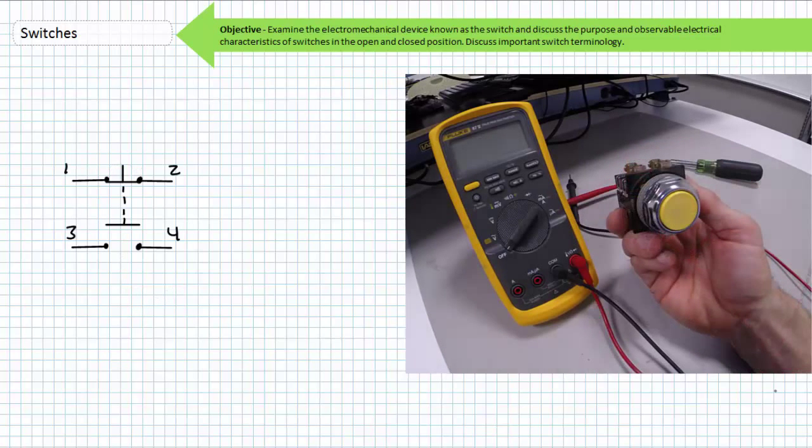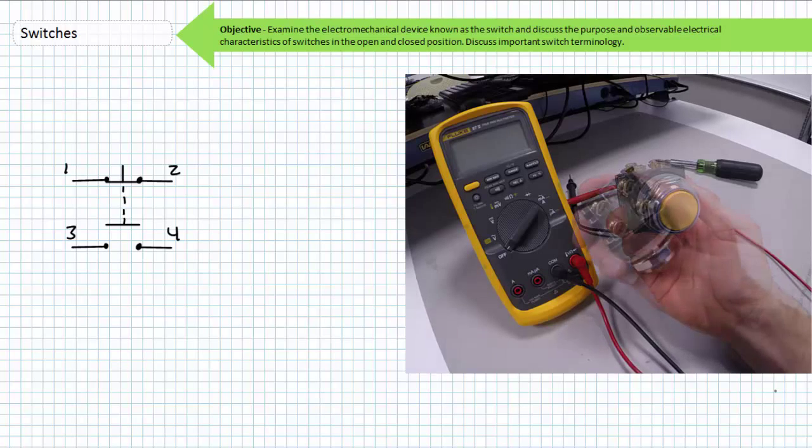Here's a push button. It's a sickly mustard-colored, slightly extended button actuator. Push buttons come in all colors, including illuminated varieties, and sometimes with flush, half-shrouded, or slightly recessed buttons. This particular switch has 4 terminals, almost identical to our last emergency stop switch package. One pair of terminals being a normally closed switch from 1 to 2, and the other pair of terminals being a normally open switch from terminals 3 to 4.